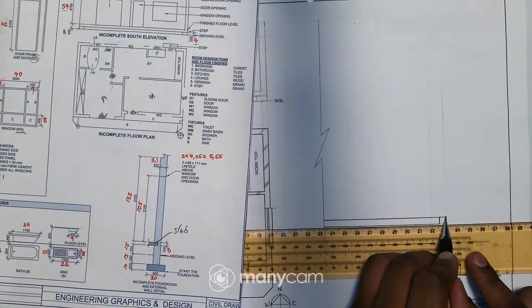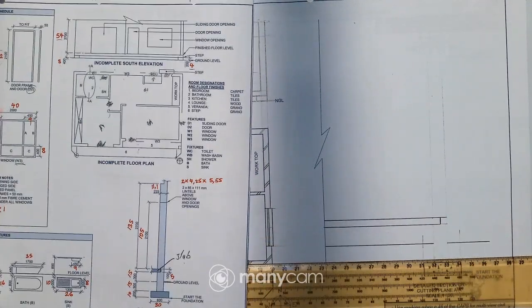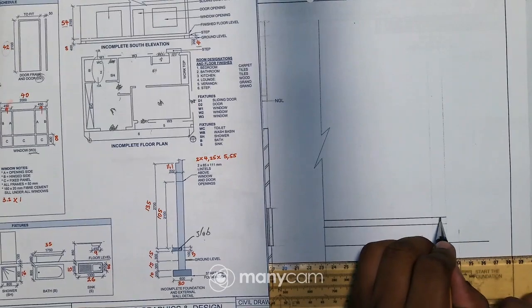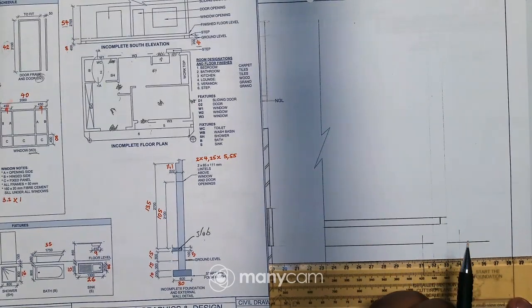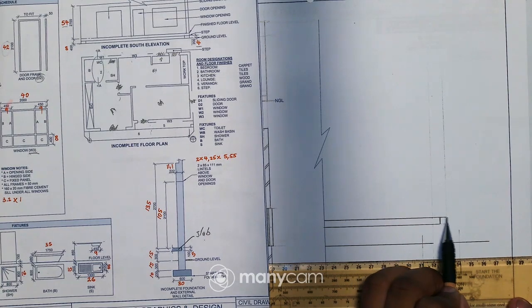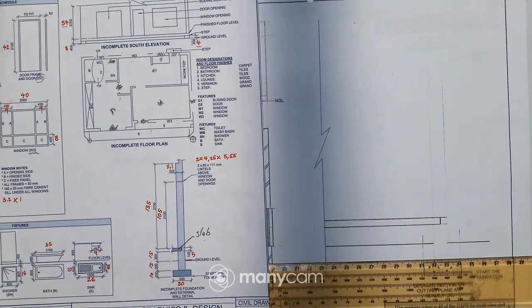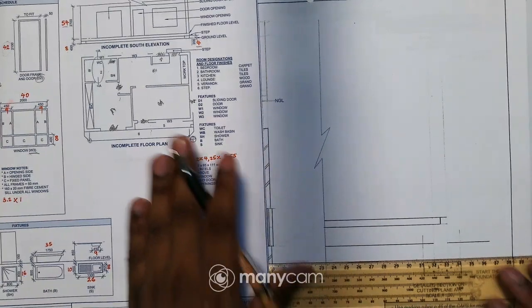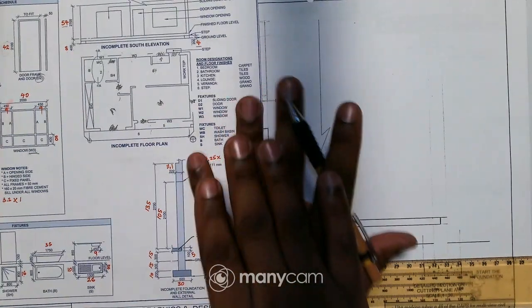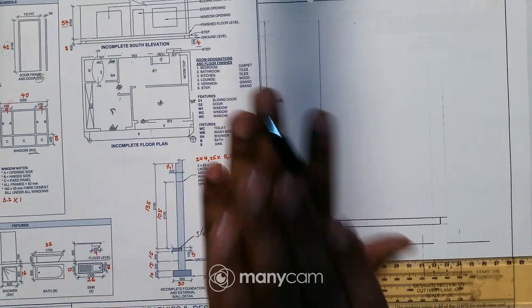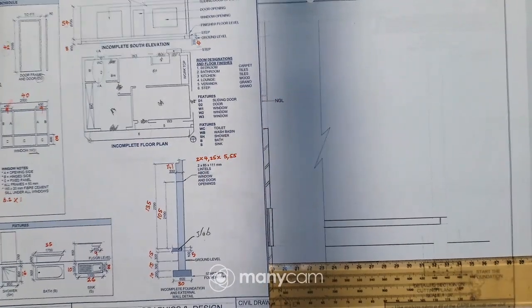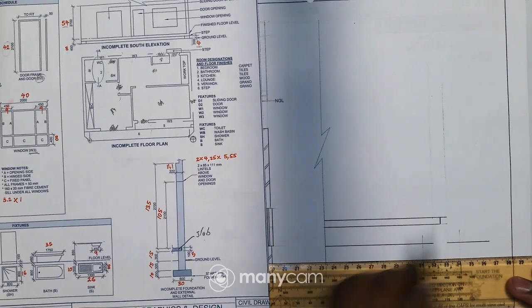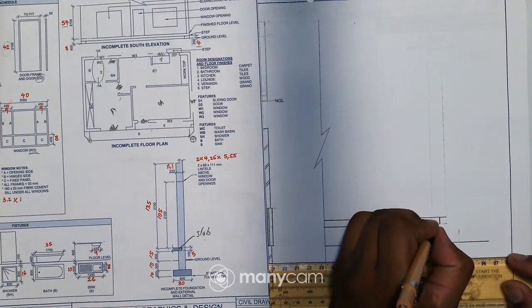And if you check, I've drawn a line from where the wall starts there. Maybe someone is asking, why is Minir drawing a line from there while the slab starts there? So I'm drawing this line because obviously we have to add what? A DPC there. A DPC is like black plastic that is placed before you build the wall, right? So the black plastic is called what? A damp proof course.